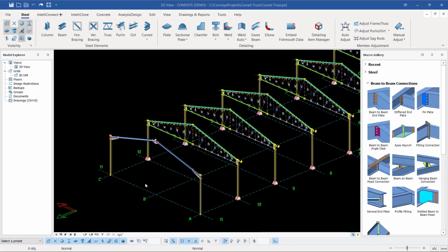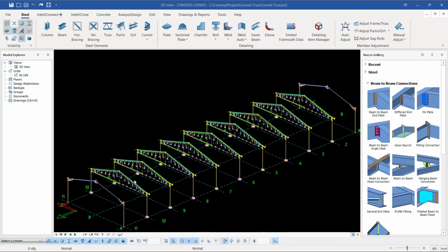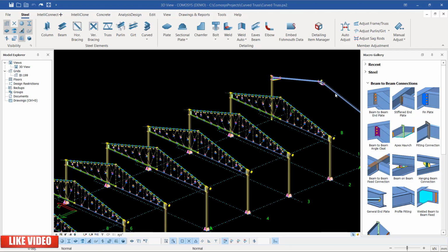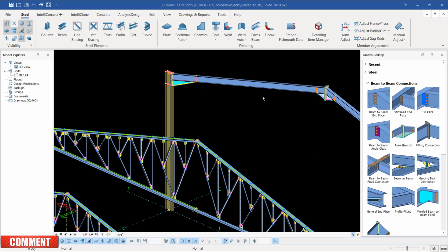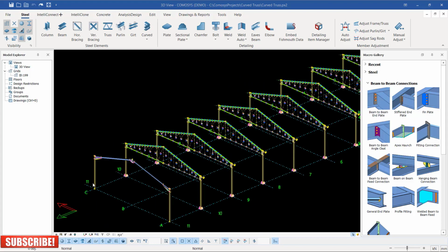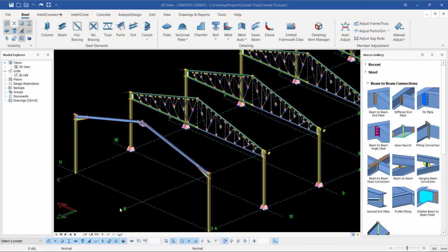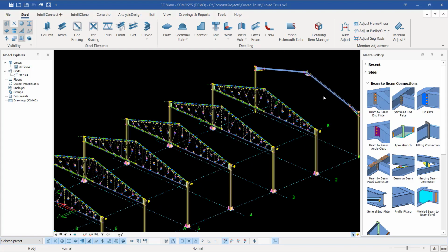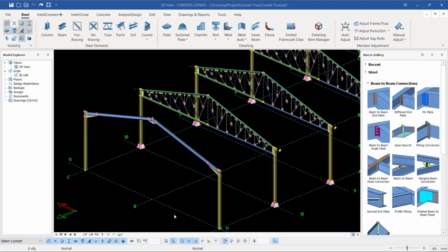So in here, we had a truss all the way for this particular structure. We decided that putting the truss at the end of this gable will make it very hard for us to put cladding at the end of the gables. So we've decided just to place the portal frame at both ends here so that we can now place our gable columns, then we place the cladding rails.